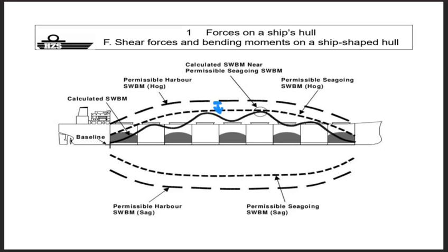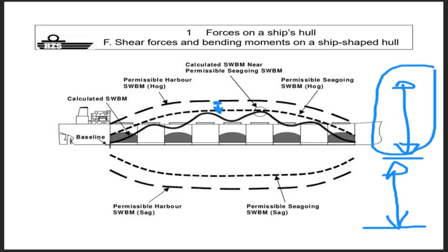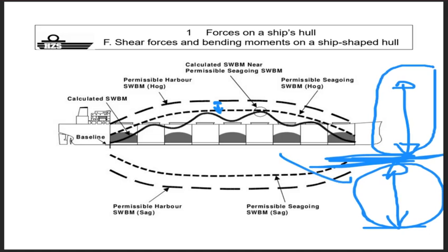The limits given by naval architects are always described as still water bending moments. Why? Because in your calculations on board, you're not taking the dynamic part into consideration. It's already subtracted. All the forces which your vessel is exposed to include, of course, the static ones, which we calculated so far. But next to that, you also have the dynamic part of the waves and the wind. The naval architect already takes this into account, and he gives you limits that only consider the static part. That's why it's always mentioned as still water.